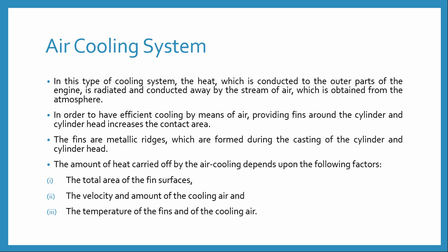So for better air cooling, the cooling surface area of the cylinder is increased by increasing the number of cooling fins on it, or by placing the engine cylinder at some inclination.